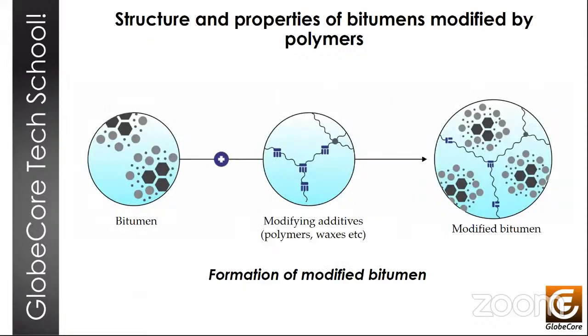So in bitumen polymer mixtures, both dispersed phases, that is, asphalt resinous substances and added high molecular polymers, compete with each other for the dispersion medium. Styrene and butadiene are compatible with aromatic and non-aromatic components of bitumen, respectively. And it is this property that explains the strong interaction between SBS and bitumen. Butadiene blocks mixing with bitumen swell and absorb a significant part of the maltenic fraction. And polystyrene blocks, less compatible with bitumen, are broken into isolated domains, thereby providing positions for later links.